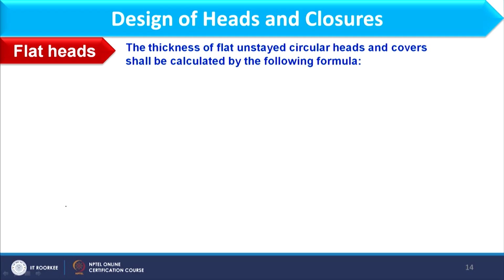So, as the flat head is the simplest one, we will start the design from that and then we will proceed towards the conical head and then the dished heads. Okay. So, let us start with the design of flat heads. Now, in this case we will calculate the thickness of flat unstayed circular heads and covers.